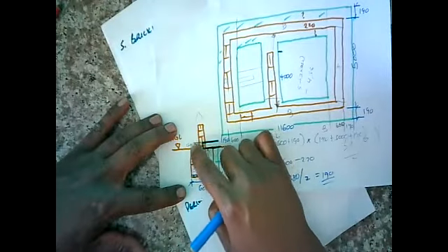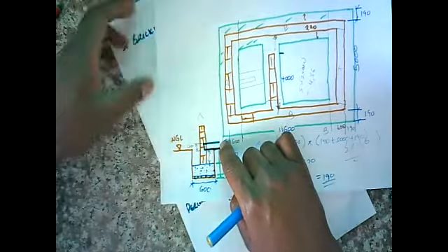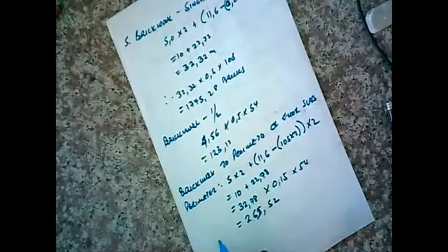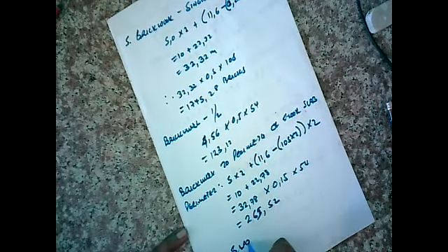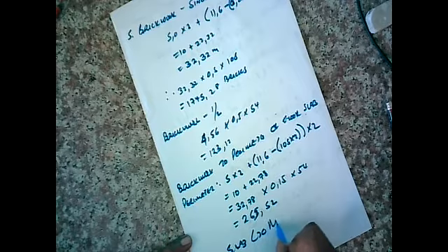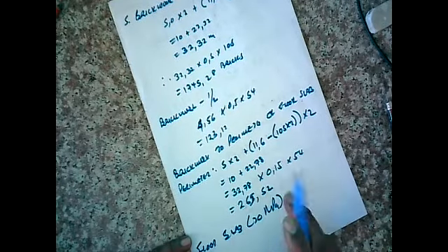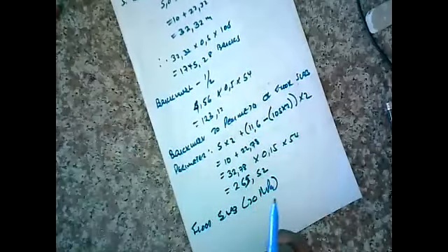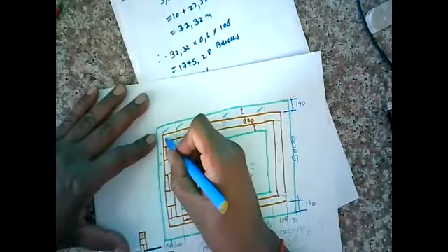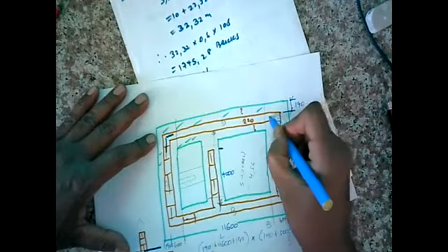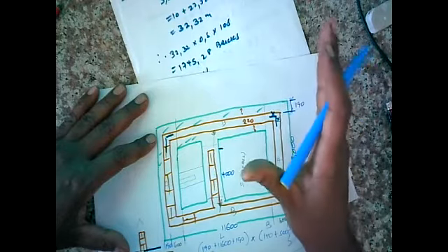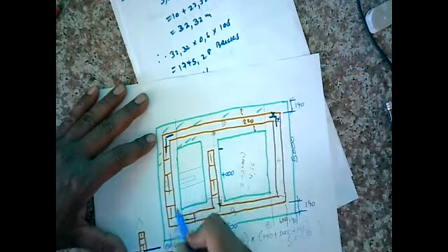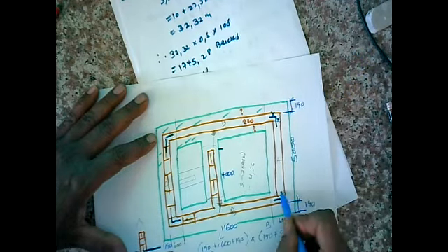All right, so we've done the brickwork. From there to there, all around there. What's next? Let's put the floor. We know the floor slab is 20 MPa. So what's the dimensions of the floor slab? The floor slab is now sitting inside this area here. Remember we just calculated the number of bricks for this section here, the formwork, if you want to call it that, and that's the dimension we're looking at.